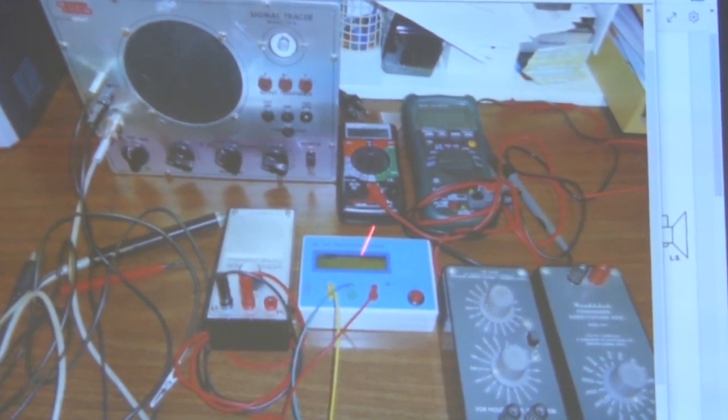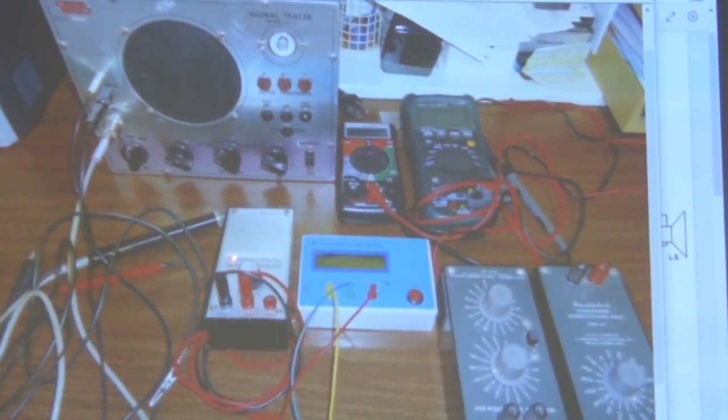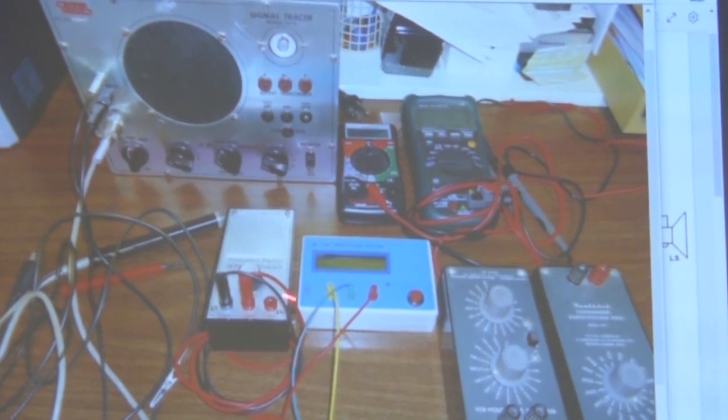So it checks resistors, it checks capacitors, it even gives you values of inductors up to 100 millihenries. So for most of radio work, except for the power transformers and so on, or chokes, it'll tell you the value of the inductors as well as the capacitors, and they're accurate to within 1%, 0.3% sometimes. And they also give you effective series resistance on electrolytic capacitors. They'll test that for you. It shows up here on the display screen. It gives you a pin readout as to which pin represents what part or electrode or component in the thing that you're testing.